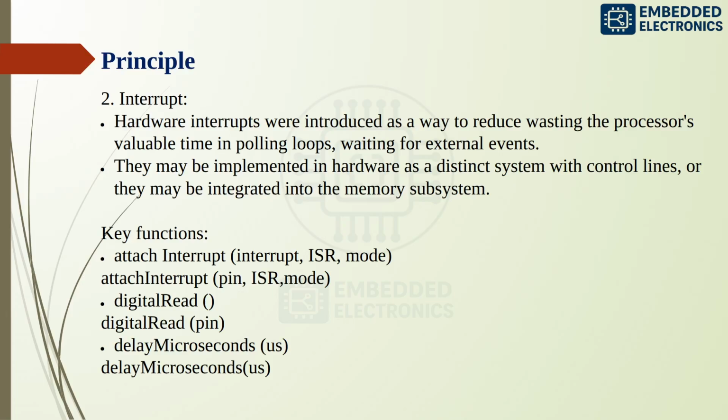It is used to connect a pin to a special function called the ISR, which runs automatically when an interrupt occurs. When a specific event happens on a pin, Arduino immediately runs the ISR function. The ISR must be short and fast. So delay and millis do not work inside the ISR. Here we are using delayMicroseconds.